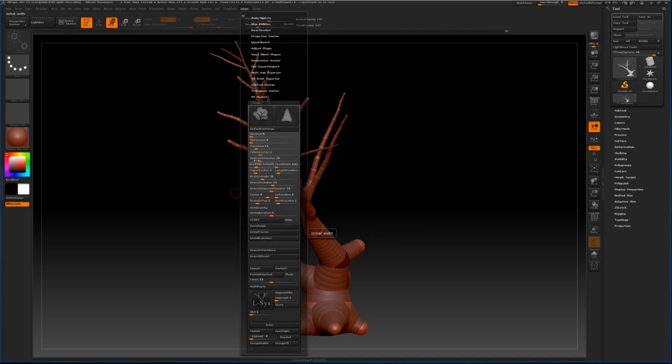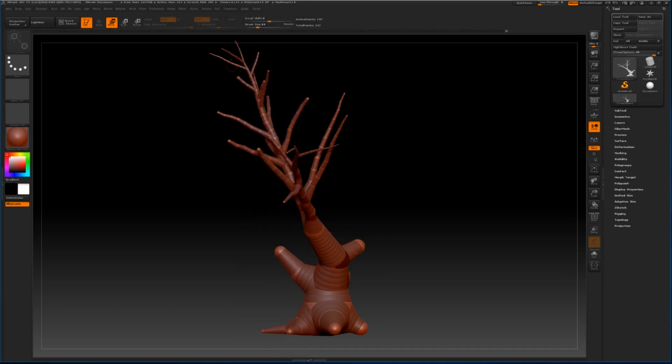So we can do a couple of things. If we change the follow factor, my understanding is that it allows the branch to change direction rather than going in a straight direction. It may curve a little bit, so that's kind of interesting. And then we can add a little bit of horizontal and vertical variation with our vertical setting and our horizontal setting there. So I'll do a setting of 20 vertical, 20 horizontal with a variation of 10, and we can see what that will give us.